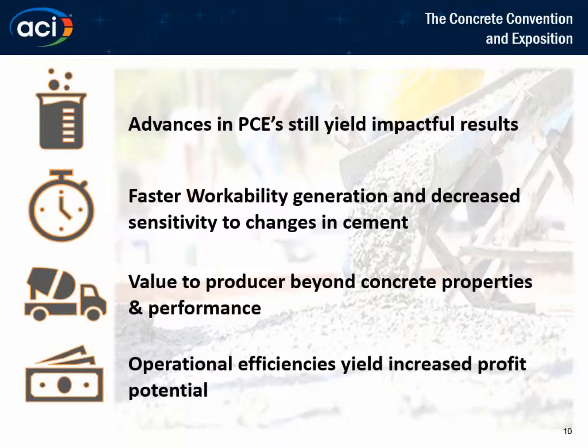Slump retention? So, yes, overall, these were examples, and as you saw, some of the workability came down over time. That's in highly demanding designs, especially with higher alkali cements. We did see somewhat of a loss of workability quicker, potentially, over time. In other instances, we did not see that. So it's more dependent on the mix design and the application and your total polymer delivered.